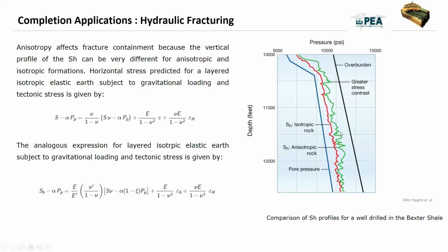So in unconventional reservoirs, be careful using the isotropic approach, which is very dangerous, because the anisotropy is very important, and in the anisotropy approach you will use the far field stress influence, and also the anisotropy of stress load, and also the intrinsic anisotropy due to heterogeneity of the reservoirs.